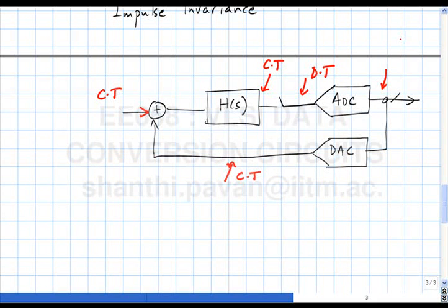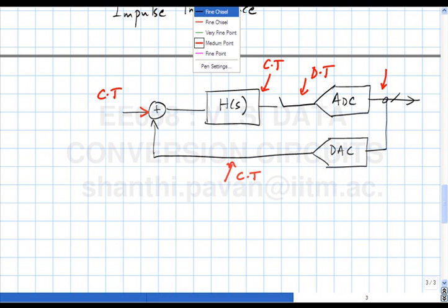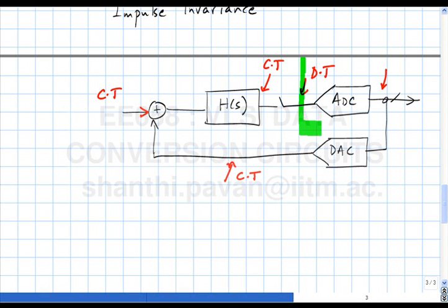Alright. So this family of converters where the loop filter is realized using continuous time circuitry but made to look like, as far as the loop is concerned, as far as this quantizer is concerned here, the quantizer can't figure out if there is a continuous time loop filter or a discrete time loop filter up front, right? Because magically the H of S has been chosen cleverly so that it is indistinguishable from the discrete time L of Z that we would have put there if we were realizing a discrete time delta sigma model. Does this make sense?